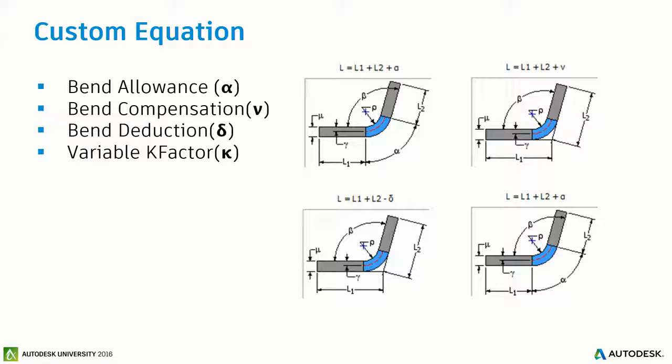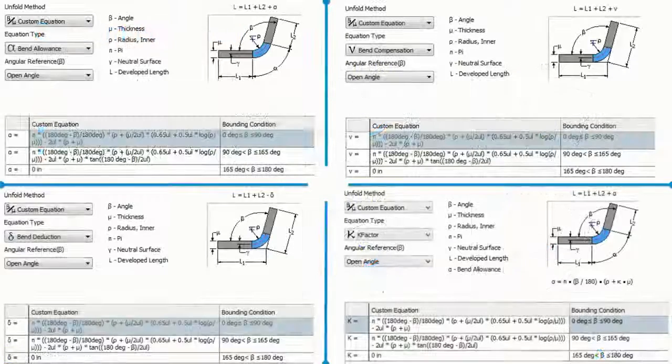But it doesn't matter, since which equation you use is based on your manufacturing condition and your material. In each equation, you have the opportunity to define the formula and specify the bend angle, and you can edit each one or add your own in the specific range.